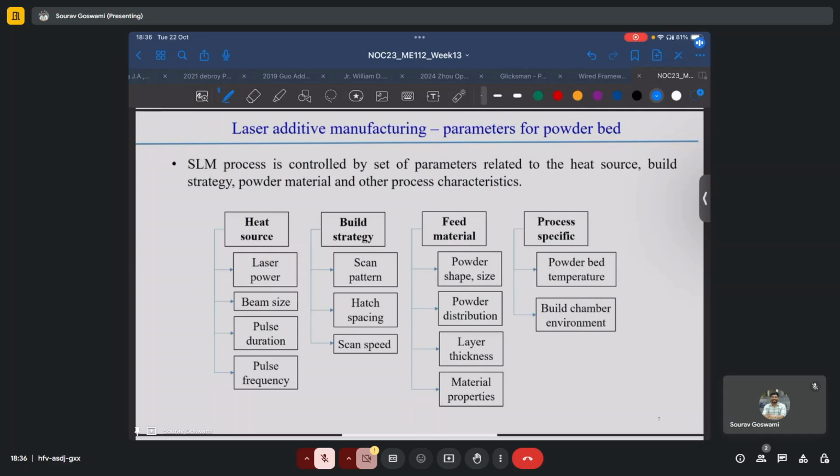Then comes the hatch spacing, and we also discussed how there exist some geometrical models for predicting the optimum hatch spacing in order to have an almost planar layer of material. And we saw how typically it is equal to two-third the width of a single bead. So if we keep our hatch spacing equal to two-third the width of a single bead, it is expected that we will have an almost planar layer, the XY plane.